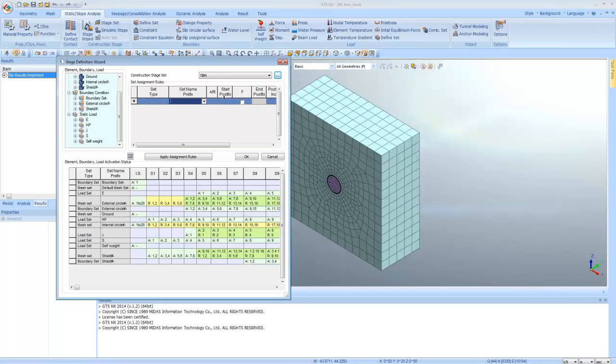For example, if a mesh set specified from, let's say, final core 1 to 12 is selected, and the final core is removed at the second construction stage, with the other cores removed in sequence after each step, the first used set number is 001, so the postfix can be set as 1. That is what it means.